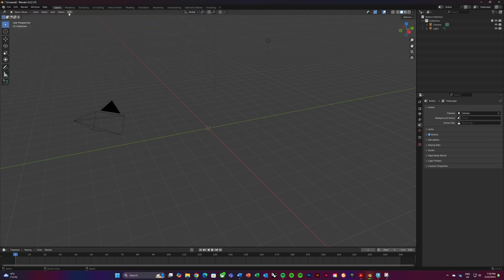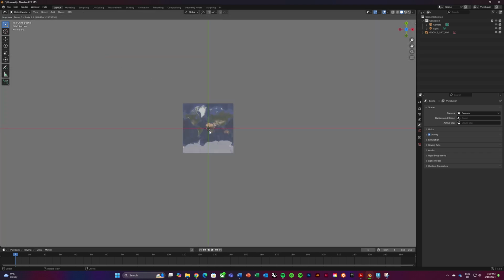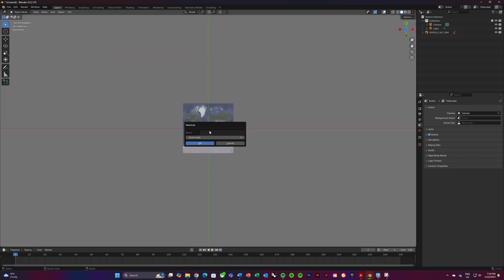Alright, so what we want to look at is these GIS tools here. To start off with, we want to go to the base map and look at the options here for the source and layer for the satellite, but we're going to keep them the same and select OK. This brings up an interactive map in which you can locate where you want to model from and where you want to get this site information from. In this example, we're going to use Footscray.